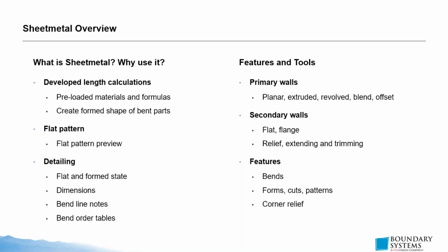And the second reason, which I think is more important and more of a time-saving and effort-saving feature, is the fact that Creo is going to be doing a lot of calculations that are not going to be visible on the surface level UI of Creo. What I mean by that: when you create a sheet metal part, you're going to assign a material for your constant thickness sheets. And Creo is going to use all sorts of formulas whenever you create any sort of feature, such as a punch form or a bend.